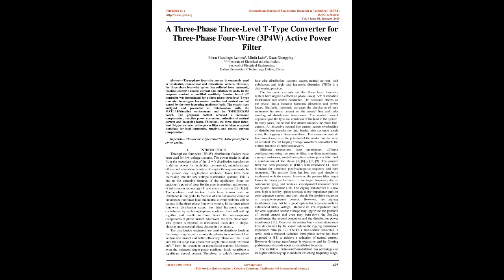Introduction. 3-phase 4-wire (3P4W) distribution feeders have been used for low-voltage systems. The power feeder is taken from the secondary side of the Y distribution transformer to deliver power for residential, commercial, manufacturing, offices, and educational centers of single/3-phase loads. In the present day, single-phase nonlinear loads have been increasing in low-voltage distribution systems. This is due to the attractive features of the appliances from the customer's point of view for the ever-increasing requirements of information technology [1] and electric traction [2, 3, 4].